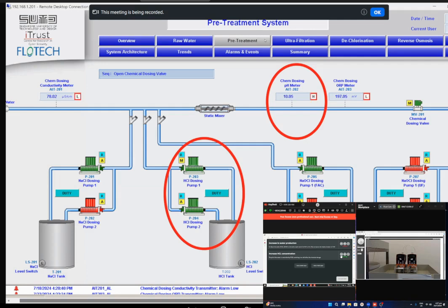And this is a replica of the Florida water treatment plant attack, which happened a couple of years ago. So this is also a replica of a real world attack, and we can see how easy it is to inject chemicals into the pump by just turning one pump and one valve from automatic to manual mode and opening it. So we can see the pH reach 9 in front of us, from 10.01 to 9 soon. And you can also see on the CCTV screen that the pumps corresponding to it are blinking green.